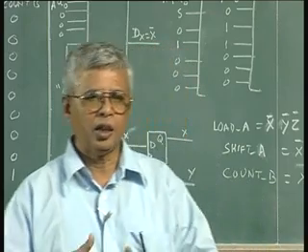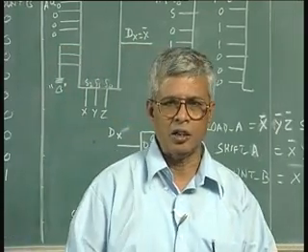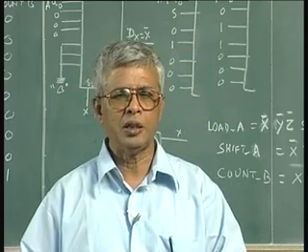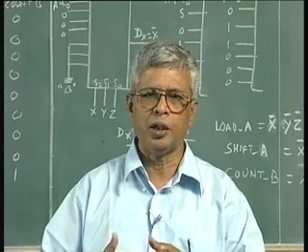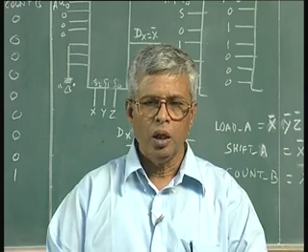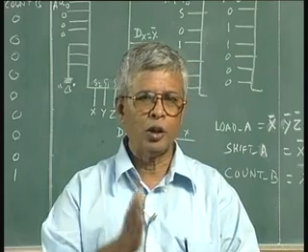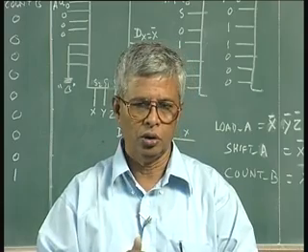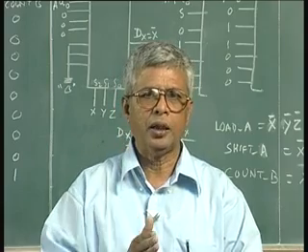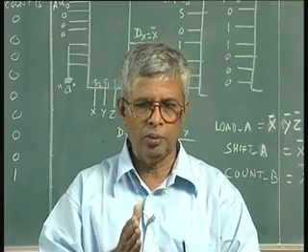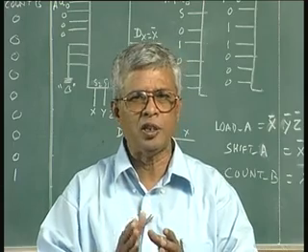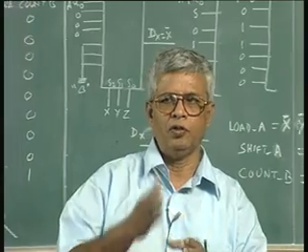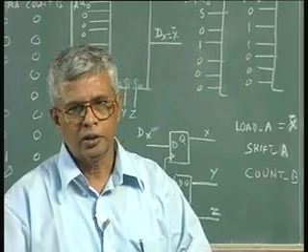A circuit can be a combinational circuit or a sequential circuit. A sequential circuit goes through various states, and its behavior depends on the present state, the input, and the past output. Now, if it is all done with reference to a clock, with the clock period as the basic driving force, then it becomes a synchronous sequential circuit. So, something that happens in between clocks will not be recognized until the next clock pulse occurs. Mostly it is edge triggered, so from one edge to the next edge, something has to wait.